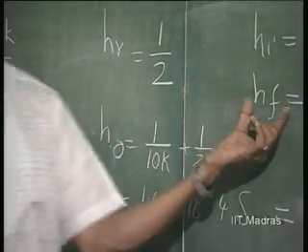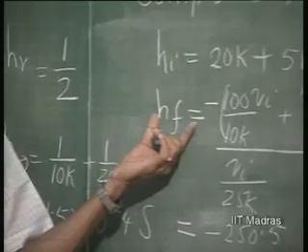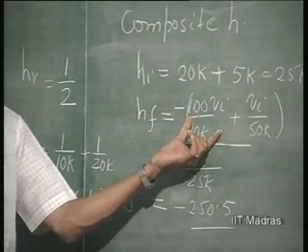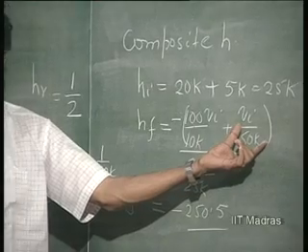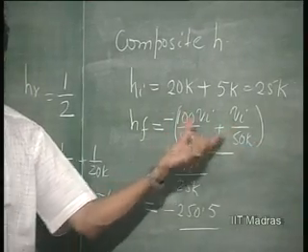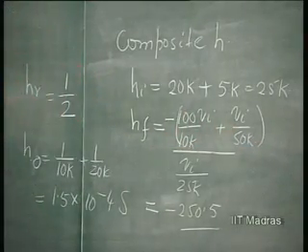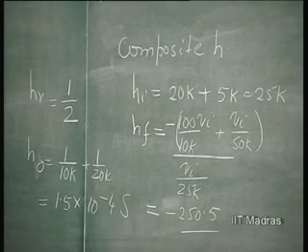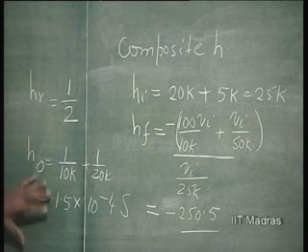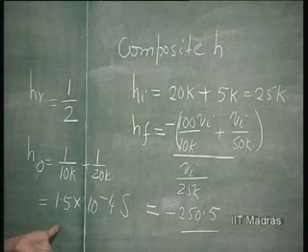Again, HF of the composite network is nothing but HF of the amplifier plus HF of the feedback network. So, all the H parameters simply add. So, if you know the H parameters of the amplifier and H parameter of the feedback network, you can simply add these to get the composite H parameter. You do not have to do it by definitions. If you know these parameters, simply add.